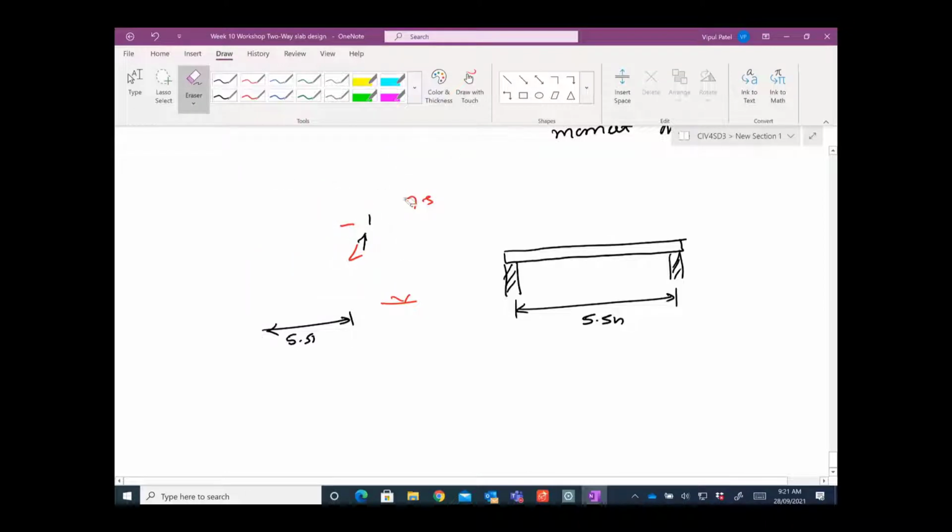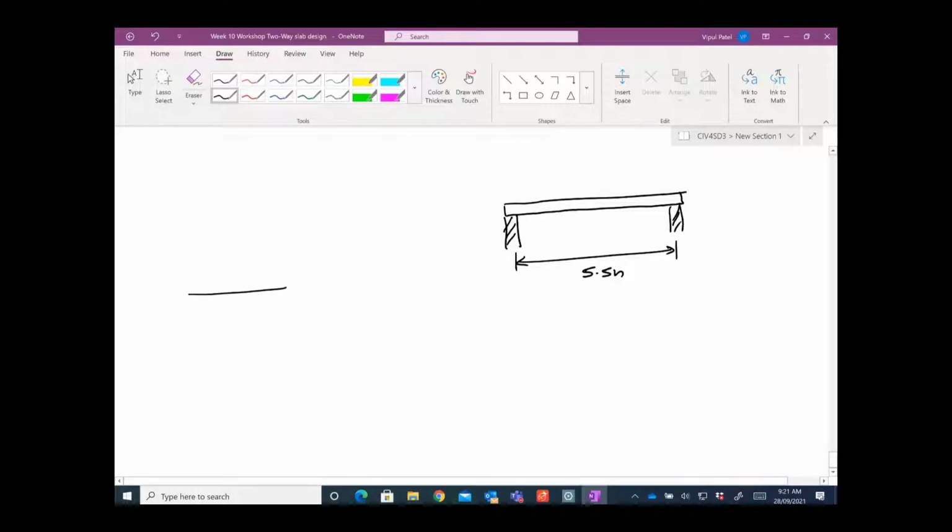So in the beam theory, we know that if you have a beam which is 1000 millimeter wide, that's what we assume, which has a 150 millimeter slab depth as the beam depth. And then we are using N12 bars, but we don't know how many bars we are going to calculate. Then you can calculate this d. I think we already calculated that d, but let's calculate here again.